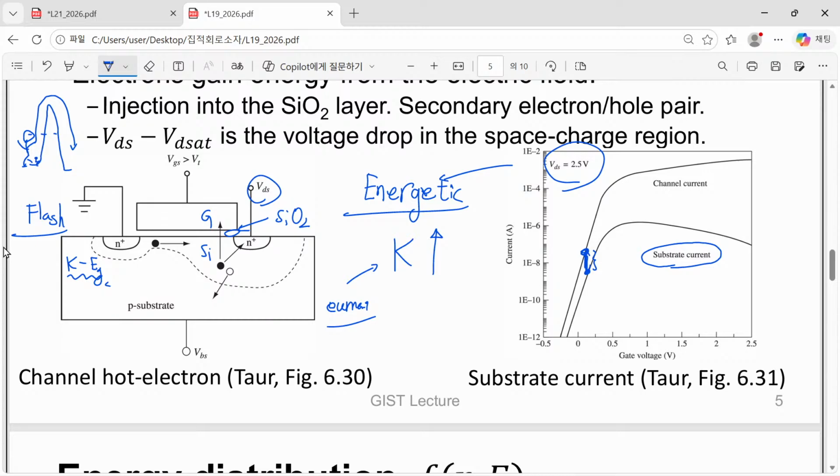So this silicon dioxide material, from the viewpoint of our normal electrons, should be regarded as an infinite wall, because its energy difference is more than 3 electron volts from the conduction band of silicon, so they can never overcome that amount of energy difference. But now let's think about a certain electron which is lucky enough.